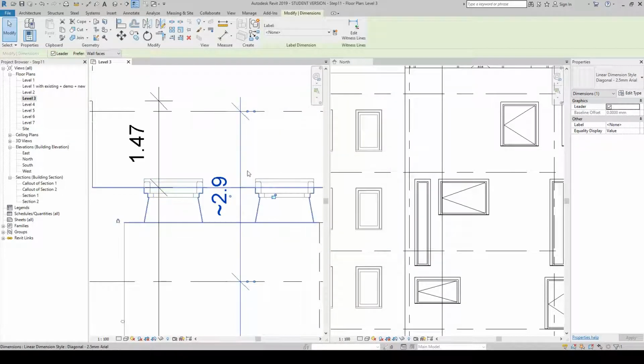we can actually change the dimensions. However, as Revit dimensions are always looking for something real, if you were to move any of these grid lines, this dimension will remain the same. Hence why you have to have the squiggly line symbol to know that this has been altered. It is advised that you don't do this, but sometimes some jobs require you to do so.